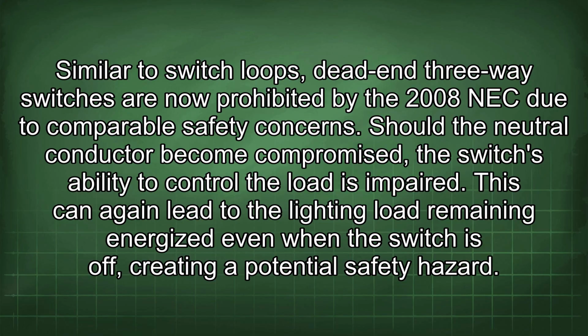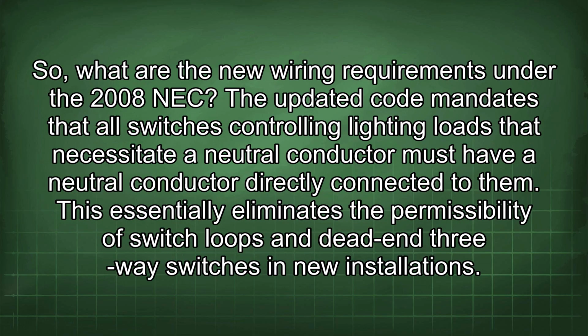Similar to switch loops, dead-end three-way switches are now prohibited by the 2008 NEC due to comparable safety concerns. Should the neutral conductor become compromised, the switch's ability to control the load is impaired. This can again lead to the lighting load remaining energized even when the switch is off, creating a potential safety hazard.